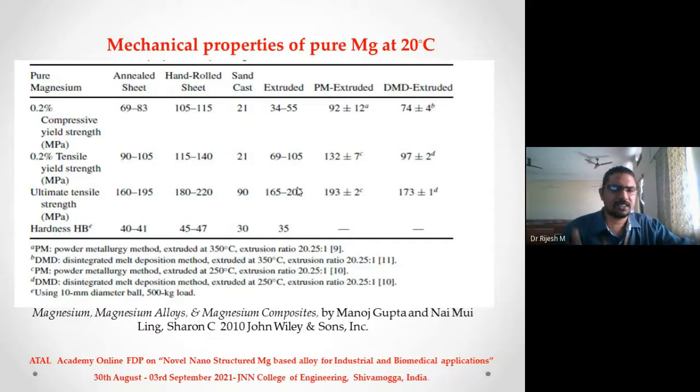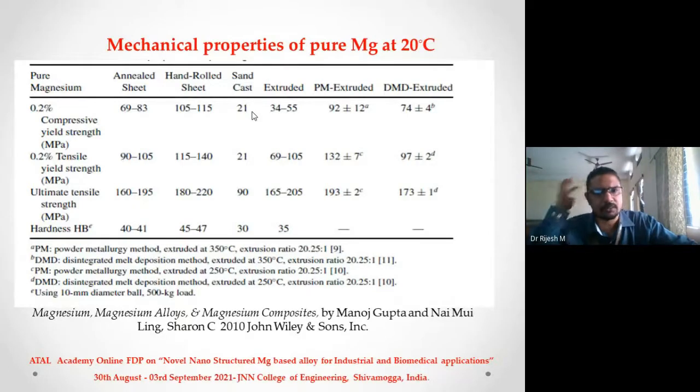But the specific strength is high. In spite of these things, the specific strength is high. Now, what you need to understand is that the specific strength of this material is high not because it has very good strength, but just because the density is low. Got it. Sometimes in engineering, we have to rework on this and make sure that the strength is also good to a certain limit.